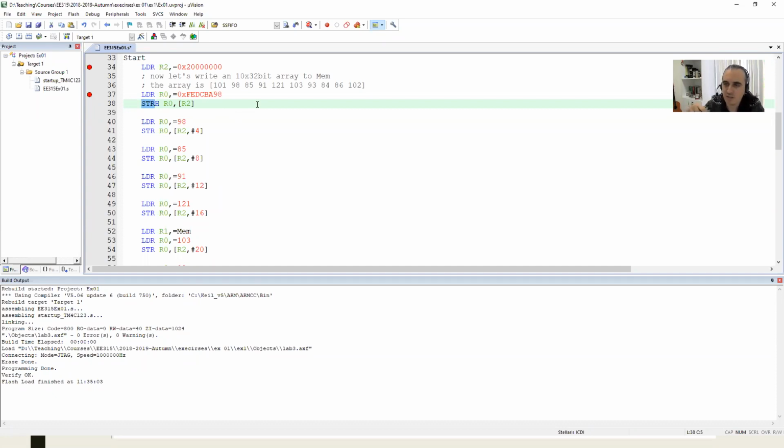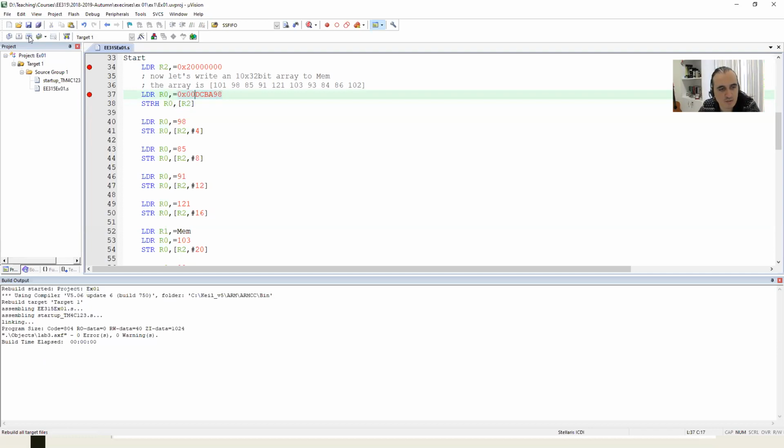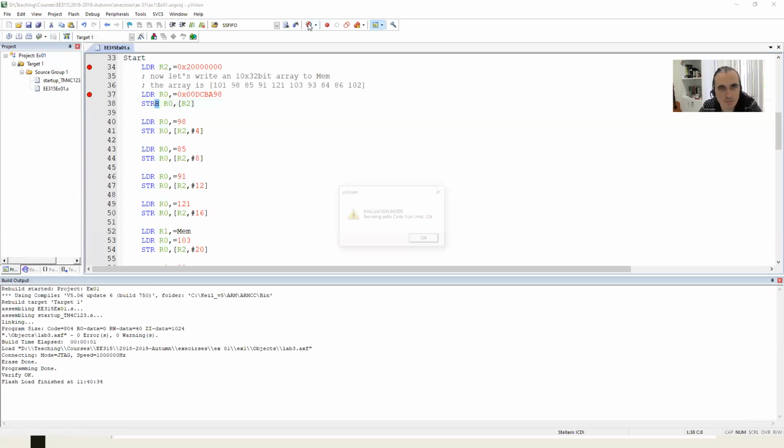We are going to make examples and it's going to settle. And please rewatch this lesson. It's going to help. I'm going to make a tricky example now, guys. I'm going to be writing a complete value. This value has more than 2 bytes actually, but I'm going to be using STRH to write to the memory. So what's going to happen? Can you see what's really happening?